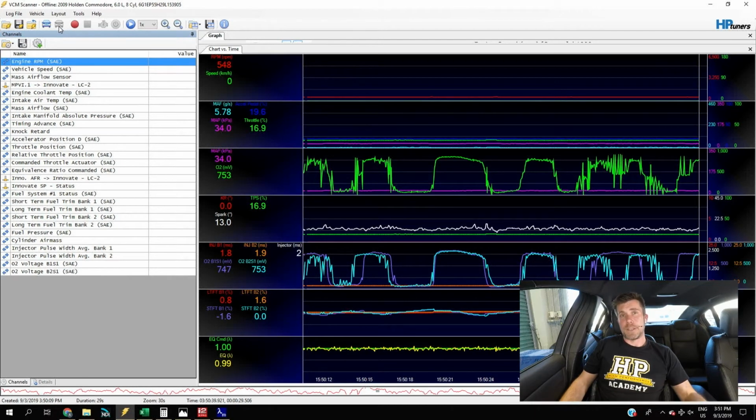If it finds the unit, it will then open up. Once you've done that, you can close LM Programmer, start scanning, and that seems to be my little trick that gets that data coming into our scanner pretty reliably. Alright, so that would be my preference. That's definitely my recommendation, and ultimately there's really no reason not to bring that data in via serial. As I've said, more reliable, but the other aspect here is that it's free essentially.